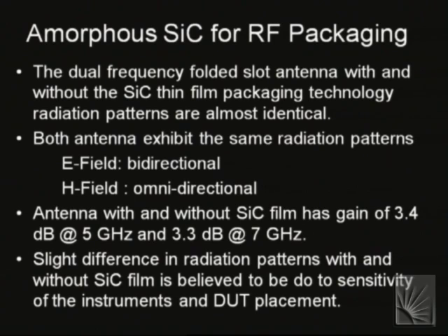Oh, and then we took these antennas that were coated with carbide and we stuck them in a gold etchant. We're like, well, it's not good as a packaging material if it doesn't protect the metal that it's sitting on top of. So we stuck it in there for 24 hours, and we saw no degradation in the coating and no loss of the gold that sits underneath it. So that simple test suggests to us that we have a thin film technology that, at the very least, is suitable to protect antennas from harsh chemical environments and motivates the work to move towards a wireless implantable microsystem.